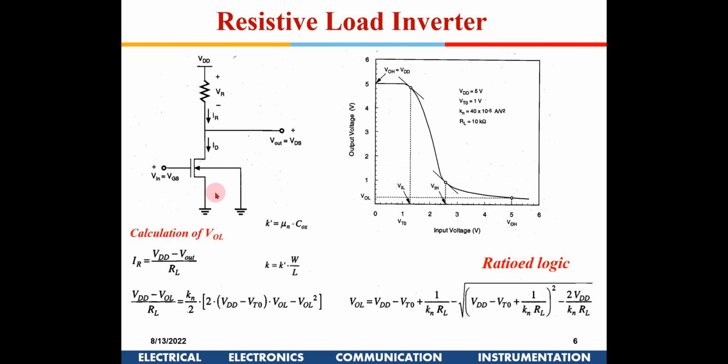So circuit to circuit, static current by definition is when the input is static. Here it is not leakage current, so I never spoke about leakage current in this. Very good, you brought this point. It should be clear to all of you. In this particular circuit, there is high static current, and that static current is on current by design. To bring this voltage to 0, I am purposefully taking some current from VDD and dropping across R. So that is not leakage current.